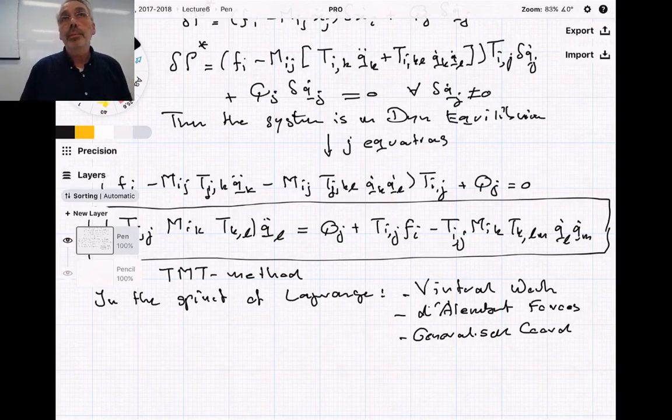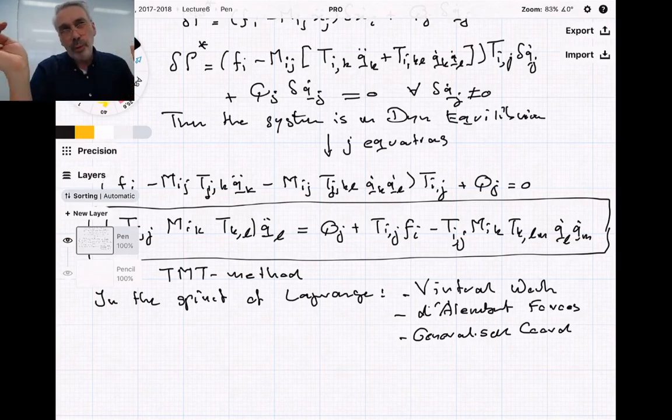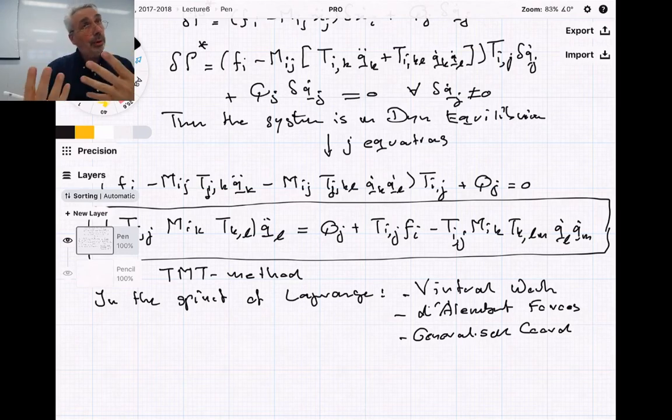Yeah, Karan. I was just wondering, this Q as well as F accounted for in the same equation. Are we accounting for the forces twice? No, we are not counting the forces twice. By definition, the Fi's are all the applied forces at the center of mass, and they have a direct duality with the center of mass coordinates, actually the velocities, through power. And likewise, if you introduce new coordinates, you also need a new set of forces.